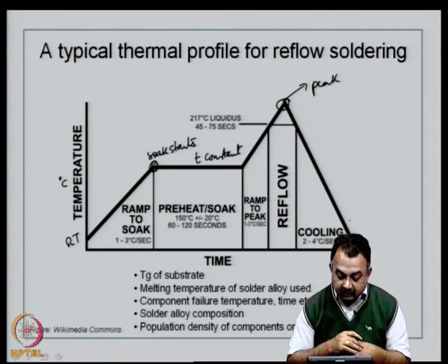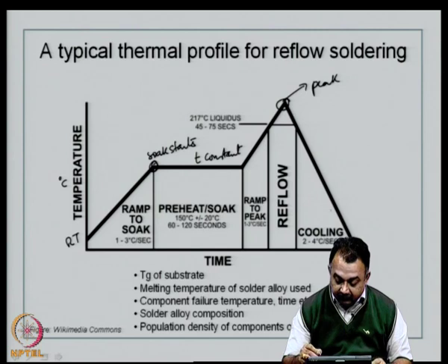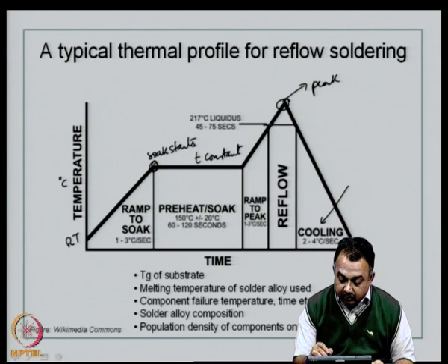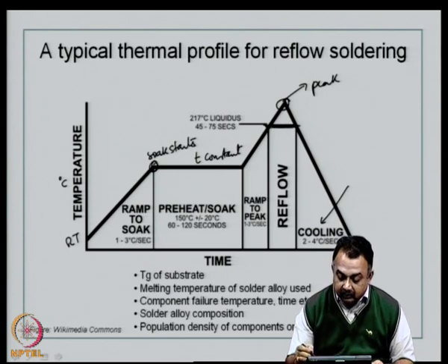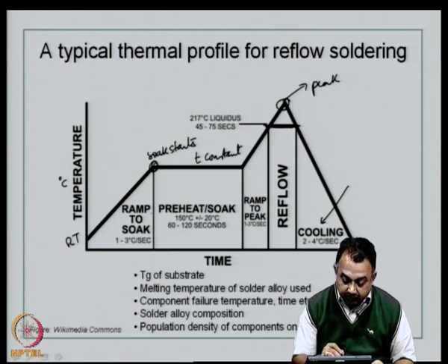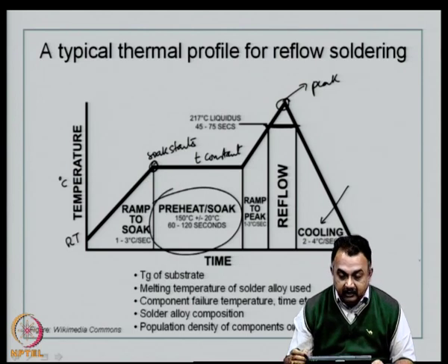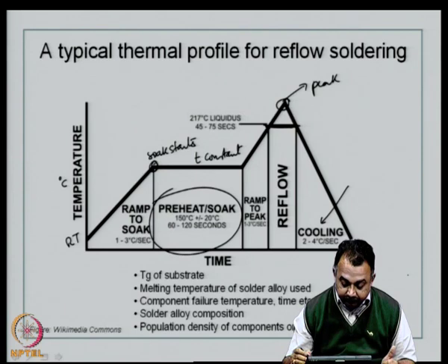So, once again, here we have cooling typically, for example, 2 to 4 degrees centigrade per second. It is up to you to have a more dwelling time at the peak reflow, or you can go up to the peak reflow and then get back to the cooling zone immediately. And then here the most important thing, visible striking difference between the previous graph and this one is that the board spends a considerable amount of time in the soaking zone.